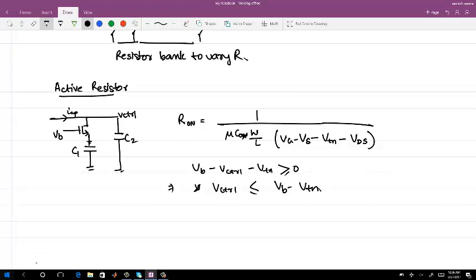So by using this kind of resistance, you actually put a limit on V control. Now how much can you increase Vb? That's another question, but by changing Vb you can do it. But in a given technology, you have a maximum voltage which you can use. Given the threshold voltage, your control voltage is limited, and if your control voltage is limited, so is the oscillation frequency. So a limit on control voltage actually limits oscillation frequency.